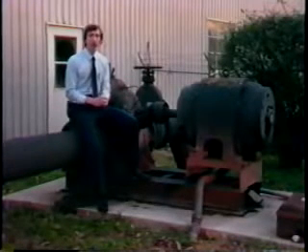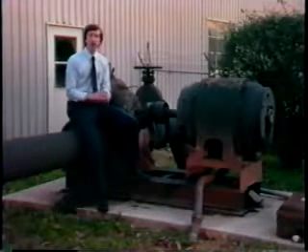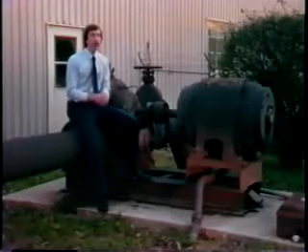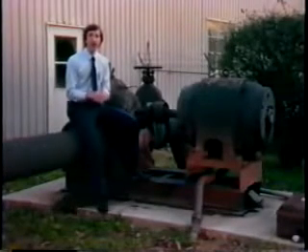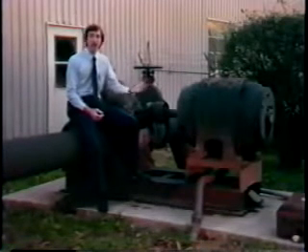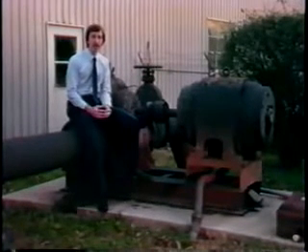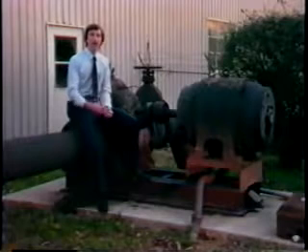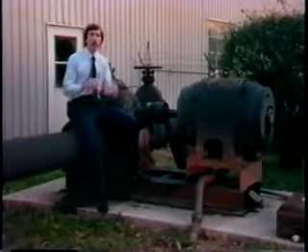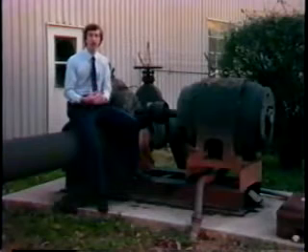What you want to do during a hydrant flow test usually is to imitate what would happen during a real fire. Therefore, you want to turn on the pumps that would be on during a fire. So if the head at the pumps drops a lot during a test, it usually means you don't have enough pumps on. So you usually, during an actual fire, turn on another pump or maybe even two more pumps.